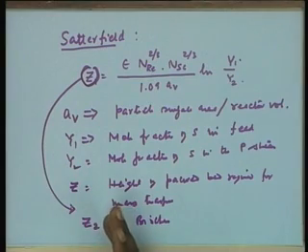But in this case the reaction will take place only at the top point where it has finally reached. Exactly, what we are saying, we are assuming here that there is no reaction within the pores of the particle, all the enzyme is present on the surface, and in the thin film there is no reaction taking place. You must appreciate the difference between internal pore diffusion and external film diffusion. While in the case of internal pore diffusion, during the transport of the substrate in the particle, reaction is also taking place, here there is no reaction taking place along with the mass transfer. It is only mass transfer.